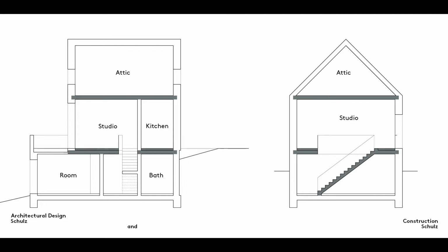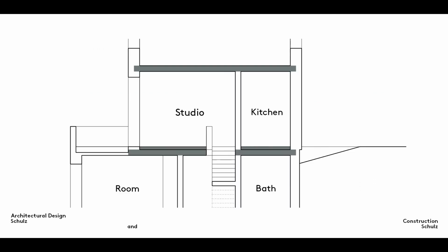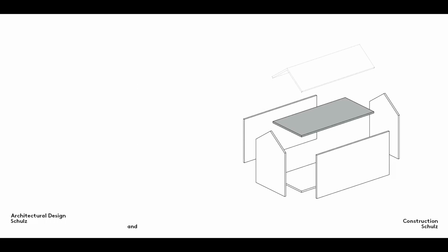Their relationship to the walls of a building is another important factor. Floors and ceilings are tied into exterior walls, while floor and ceiling coverings and finishes lie within the exterior walls. A floor ceiling is a flat element that is positioned horizontally. It both covers the room below it and forms the base of the room above it. Due to this double function, the same element may be referred to as a floor or ceiling, depending on the speaker's perspective.